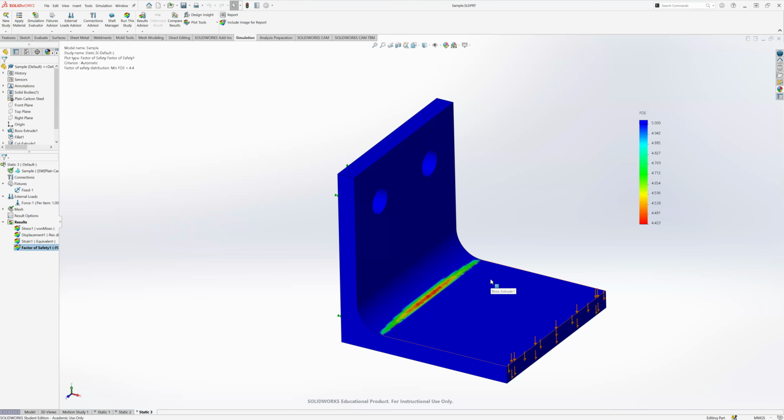Another thing, depending on the manufacturing: let's say you're 3D printing something. That's additive, so you're adding material. The more material you have, the longer it's going to take and the more it's going to cost. So in that case you definitely want to reduce material and weight. Like what your professor was saying, but I'll go a step further: it depends highly on what you're doing, how it's manufactured, and what kind of material you can get.